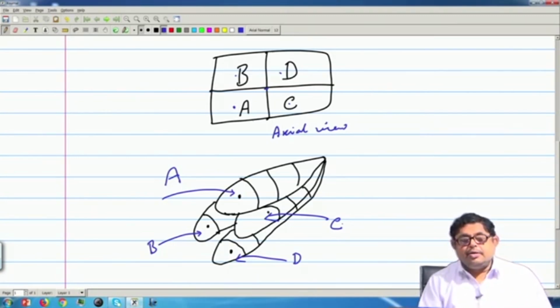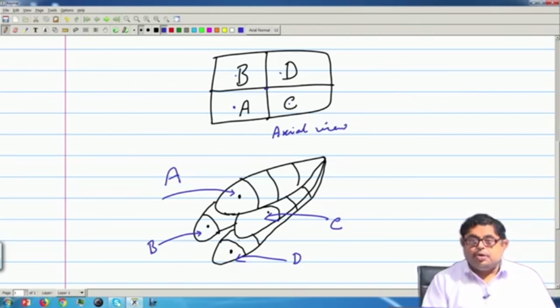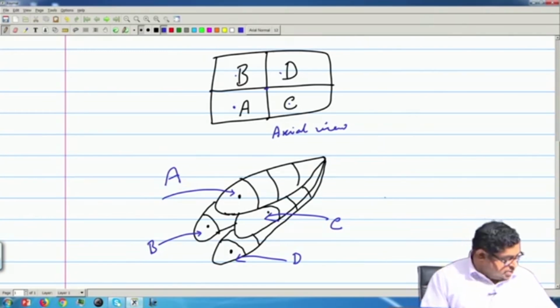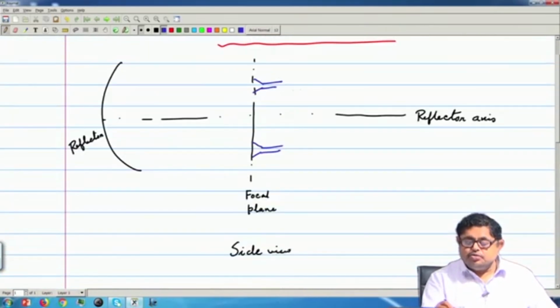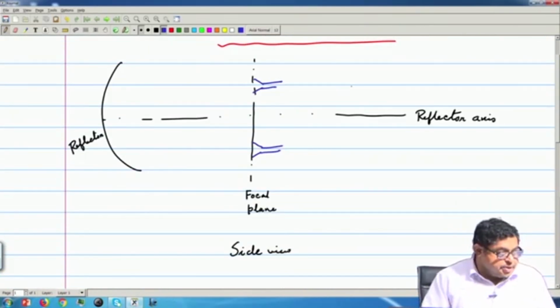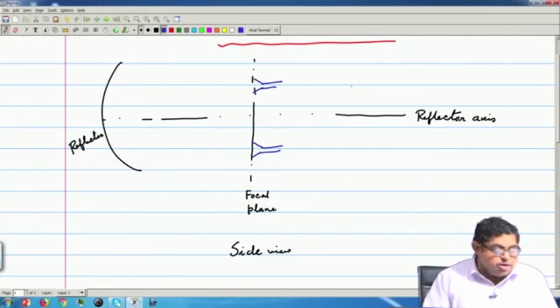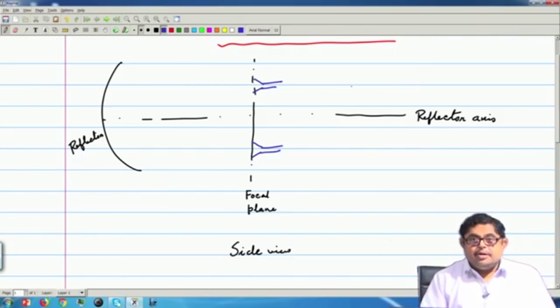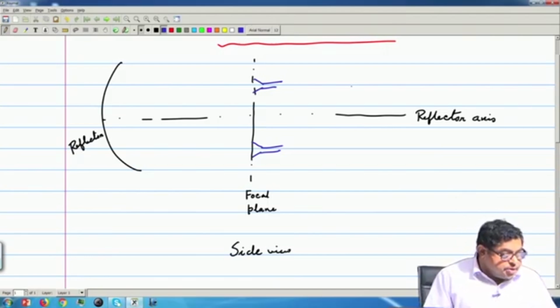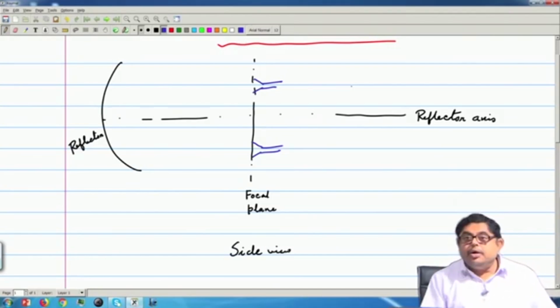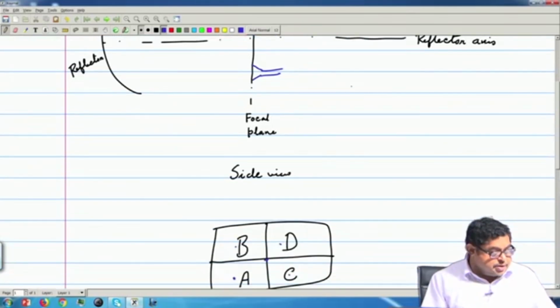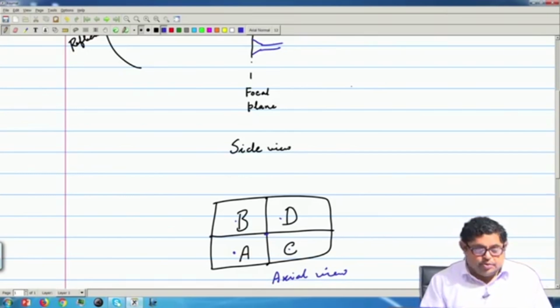If a plane wave illuminates these 4 horns, and the 4 horns are connected to 4 separate identical receivers, that means each horn is connected to one RF receiver, then due to the offset, the phase of the signal received by each receiver will be the same, but the amplitude will not be the same, because the amplitude will differ according to the beam pattern and the direction of arrival of the plane wave.